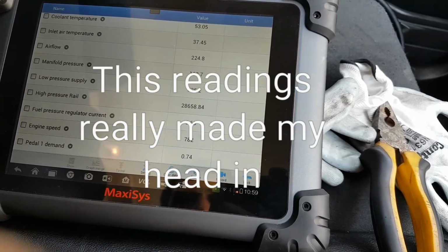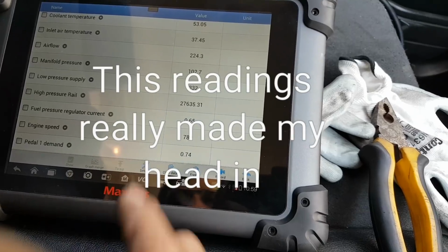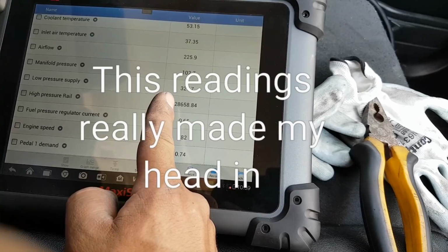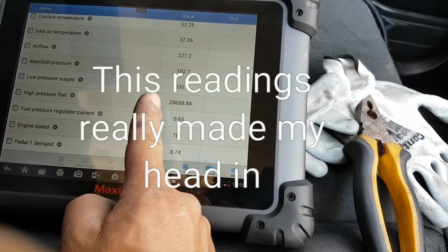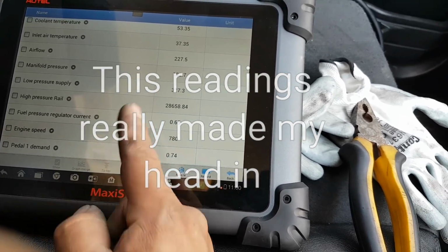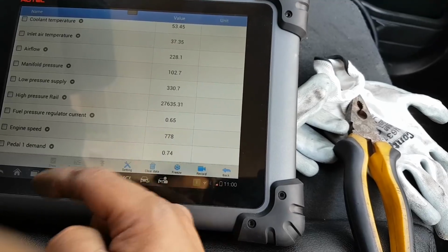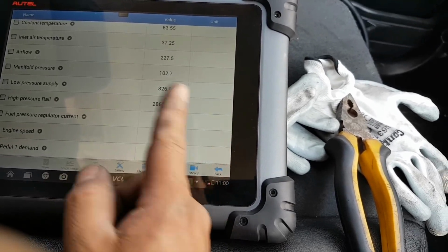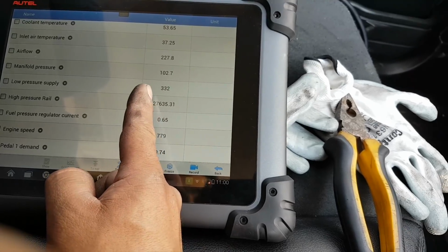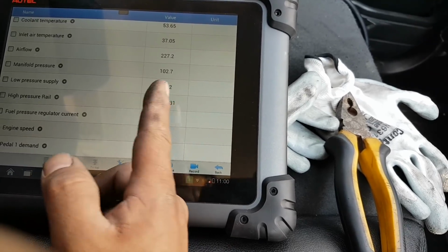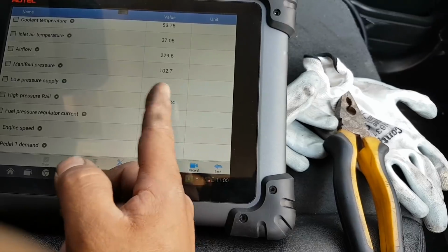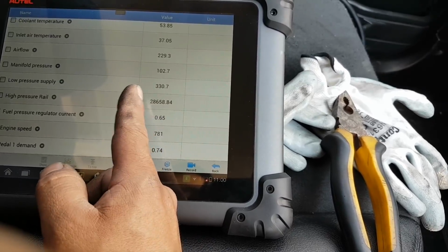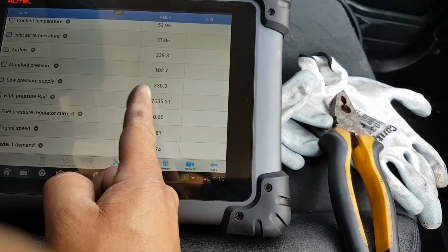Damn it. Okay, anyway, now the thing is, is the sensor now reaching that voltage because it's faulty, or is it reaching that voltage because the pump is now delivering that pressure? If I unplug the sensor, that goes to 440 here. Obviously it just goes to default fuel, as it's not connected.